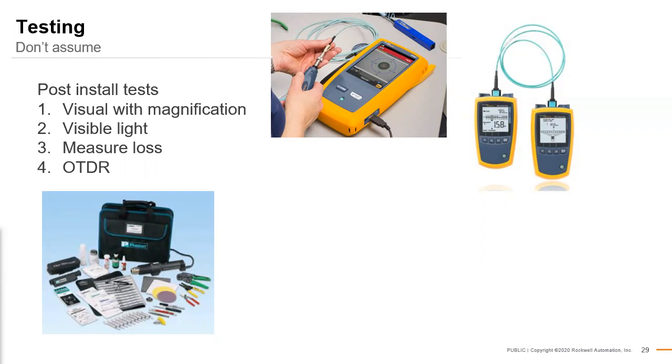It's one of the biggest things when it comes to the copper side: I've got flashing lights, therefore it must be fine. That is one of the OTDR functionalities, being able to test your fiber to its full capacity, which is extremely important. An OTDR gives you a full snapshot from point A to point B of everything that's going on in the fiber. It's cable radar. We can actually tell where you might have micro bends in your fiber using that.